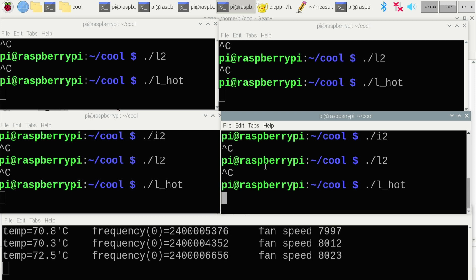When testing a cooler, you not only have to measure over a longer period of time, but above all, you have to measure very regularly and observe how the temperature goes up and down and what the fan is doing.